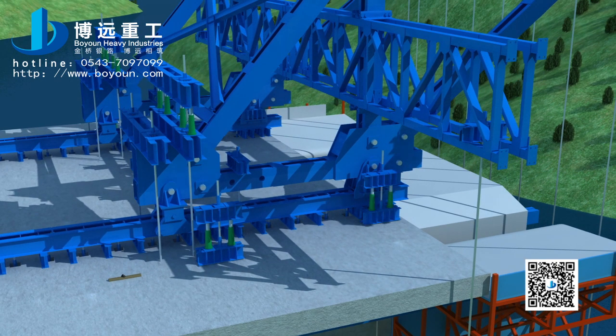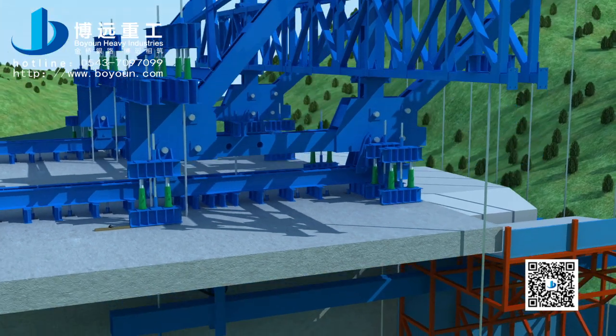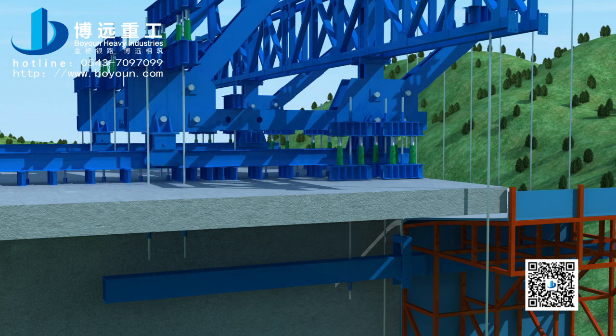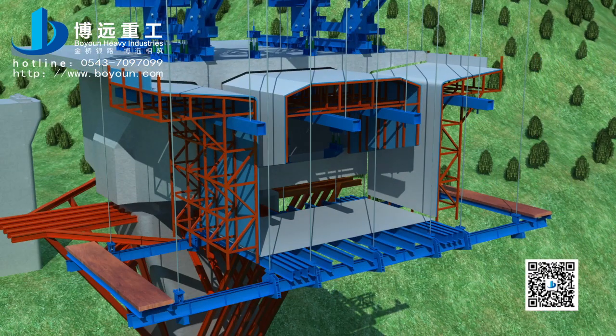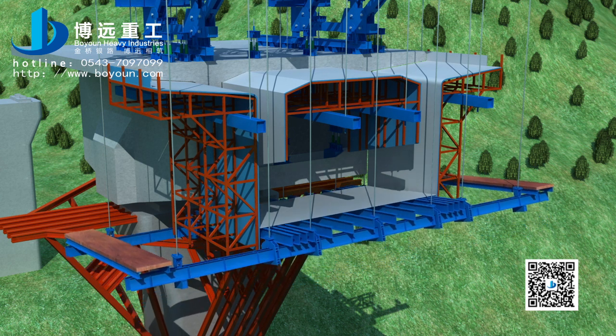Reinstall the bearing hanger rod by bearing plate to anchor the internal and external nose girder, and move the nose girder's rolling hanger frame to the specified location to anchor. Adjust the bottom support system and overall framework elevation.